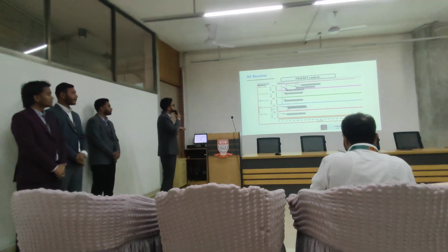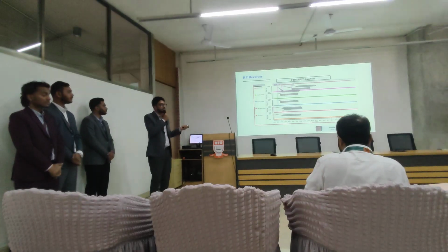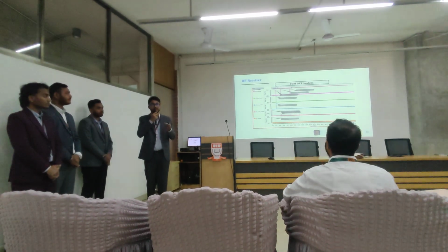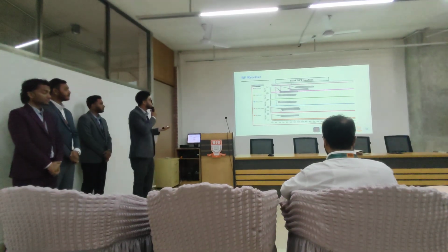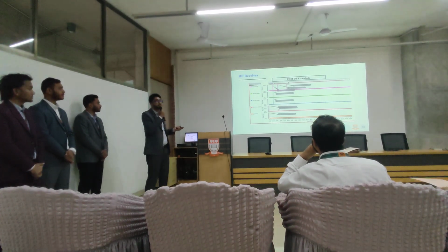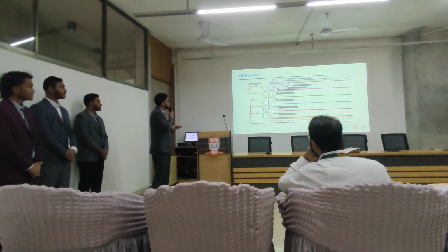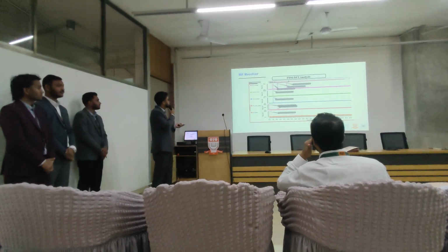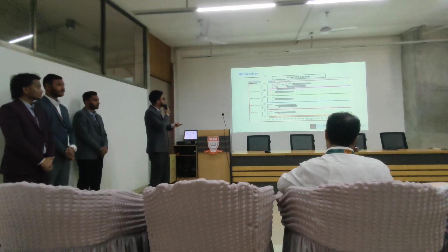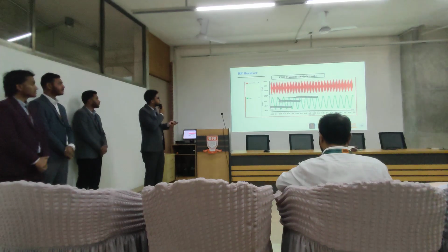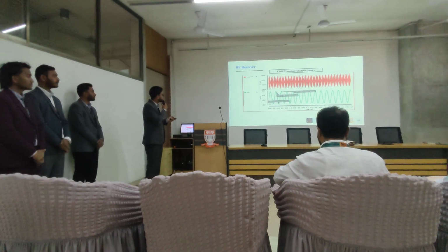The LNA boosts the signal, and the main work is done by our mixer. The mixer down converts it into two spectrum components: one is the sum frequency, which is 4.9 GHz, and the other is the difference component, which is a 50 MHz output. The LPF cleans out the 4.9 GHz component because we need the desired message signal of 50 MHz at the output. So after the LPF, we get our 50 MHz signal back.